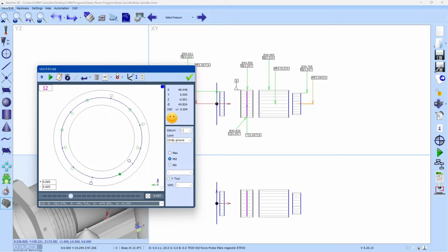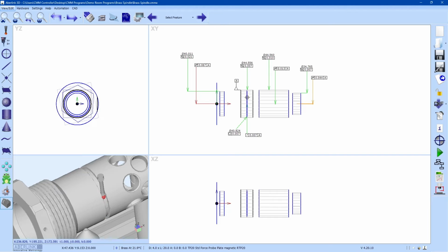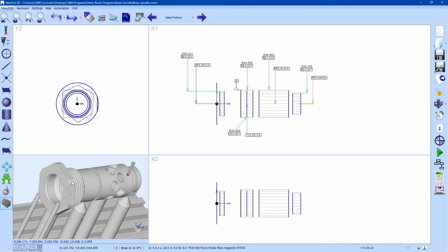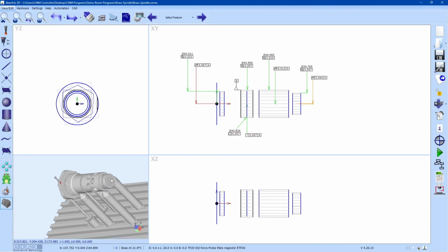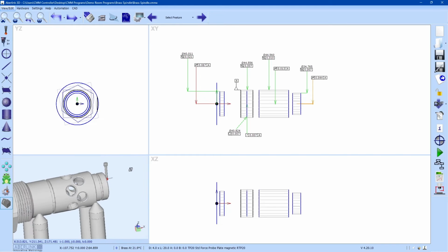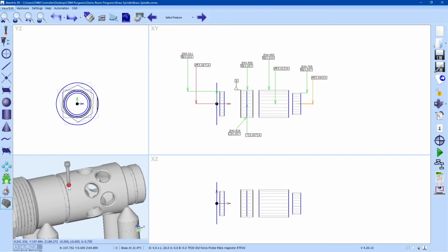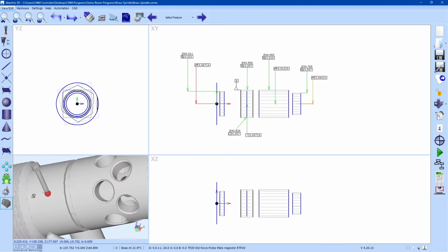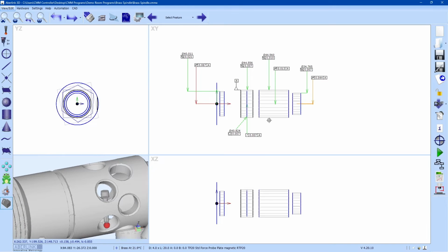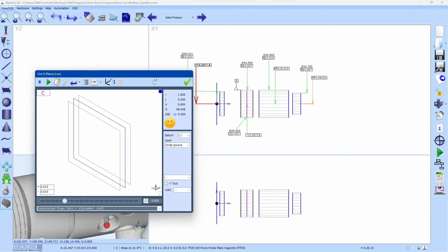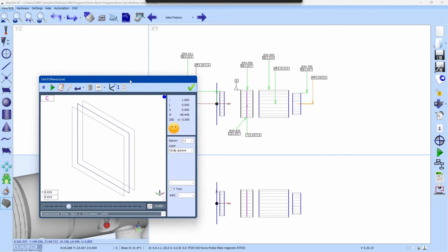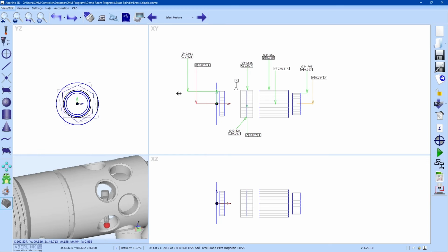And you'll see I've projected this into feature number 8. So what is feature number 8? Well, we don't actually have a plane to project into anywhere near. The options would be measured planes on the front shoulder, or the rear shoulder, or the rear face, which are still very far away on the axis in relation to this groove. So what I've done is I'm using datum A as the reference it's to. I'm using that to align it, and I'm constructing a plane. This plane has been constructed from the cylinder. So plane, spanner, double click your cylinder, and that constructs a plane perfectly 90 degrees to the axis, and we're using that for the projection.